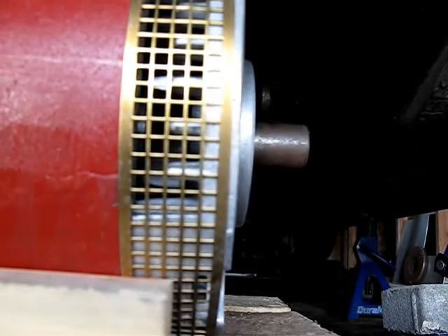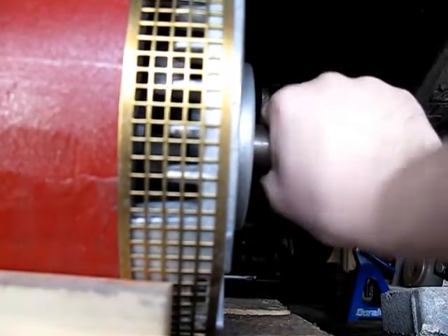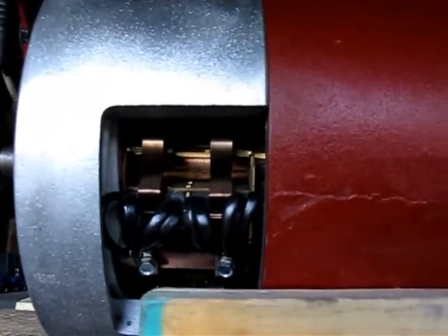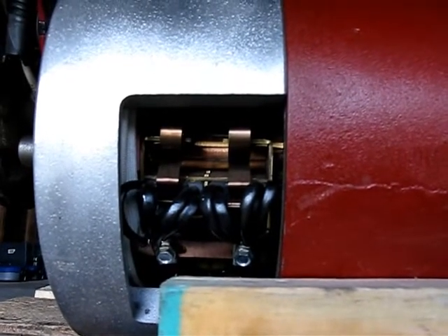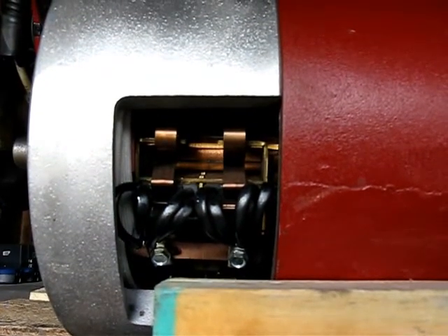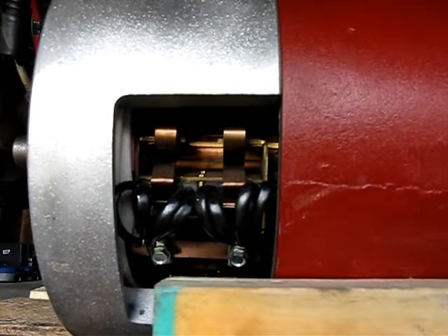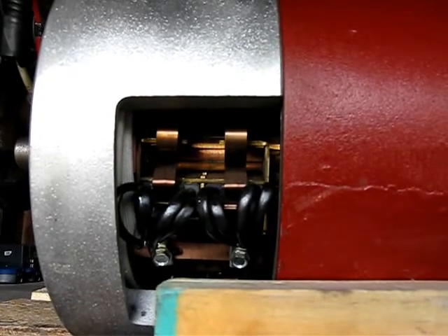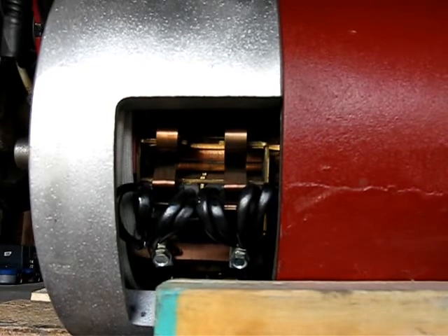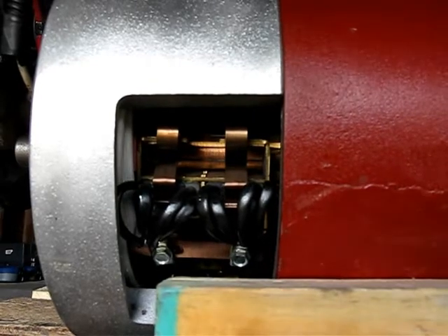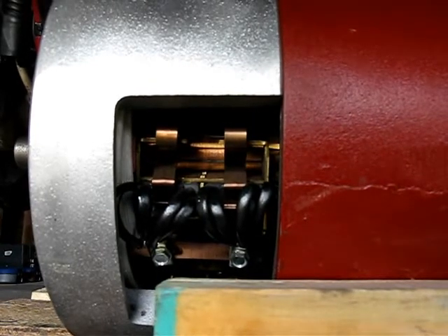So anyway, this definitely does have the fan blades in here, and you can see them spinning, and it does move quite a bit of air out of there. Also note that I did take off the cover band on this side because I wanted to have maximum airflow while the motor was doing this whole seating process and running for 40 hours straight. So I did do that, and I may rig up something for the forced air cooling later, but for right now, I think this will work just for sitting here doing the brush seating, and we'll come up with a plan after that.